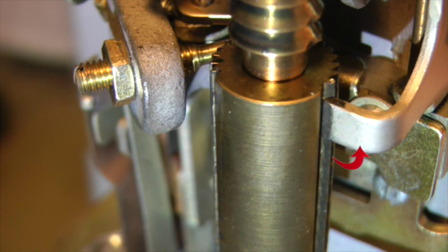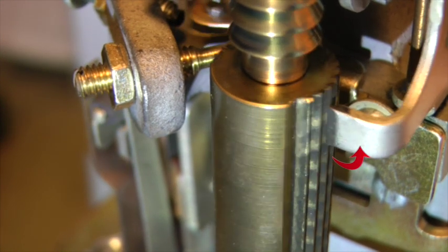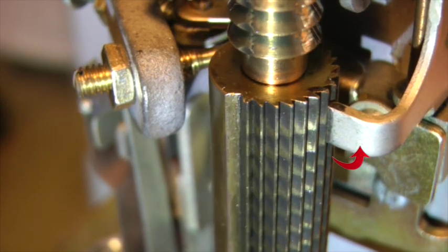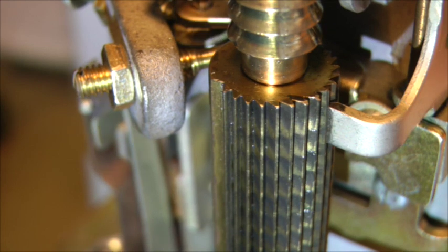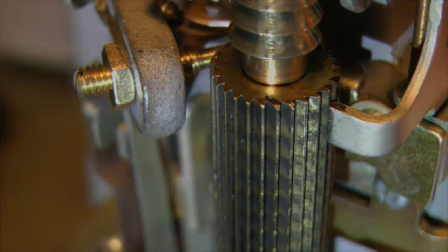During rotary stepping, the rotary dog leg prevents the shaft from rotating backwards or anti-clockwise between engagements of the rotary pawl. When rotary stepping is finished, the rotary dog leg holds the shaft fixed in its rotary off normal position for the duration of the call.